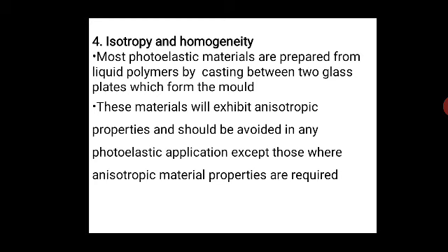Therefore, these materials will exhibit anisotropic properties, which include both mechanical and optical properties. And therefore, this material property should be avoided in any photoelastic application, except where anisotropic material properties are required.